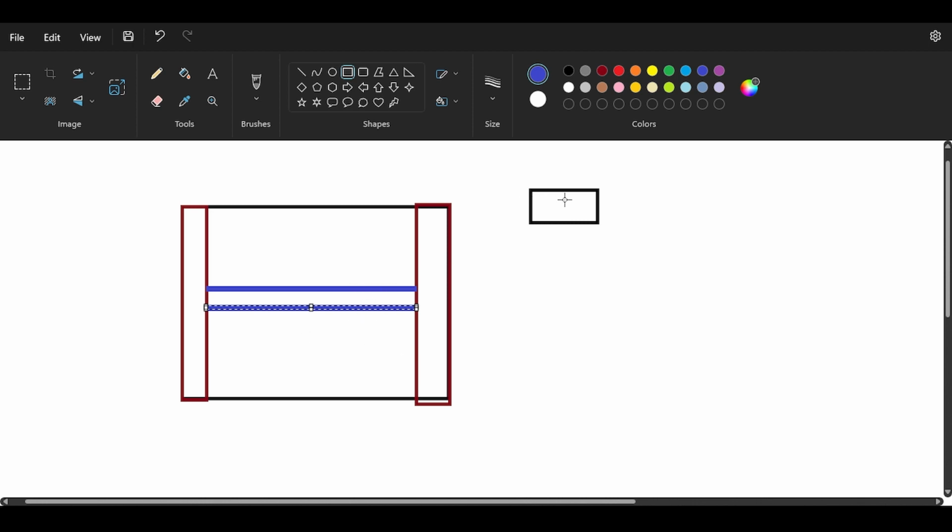I usually use the height to be multiples of the brick height. That's one thing. And the second thing is the width, and here this is a must for me. I try my best to have the width of the beam be the same as the thickness of this block, because I want to hide the beam inside the wall.